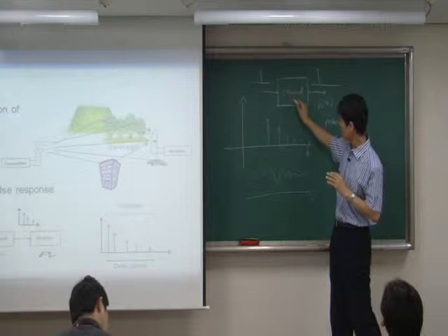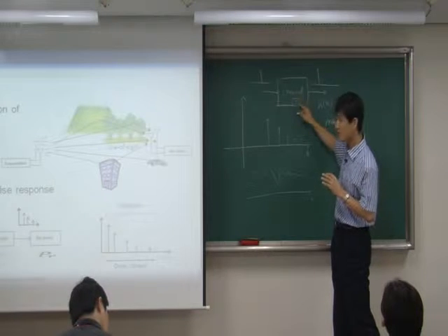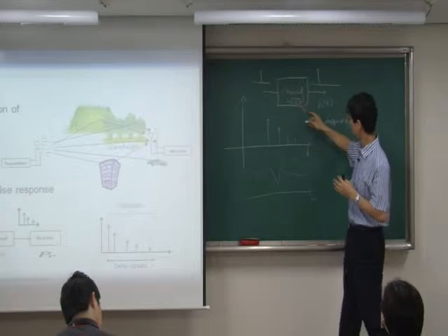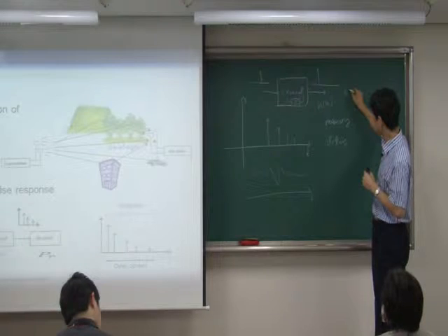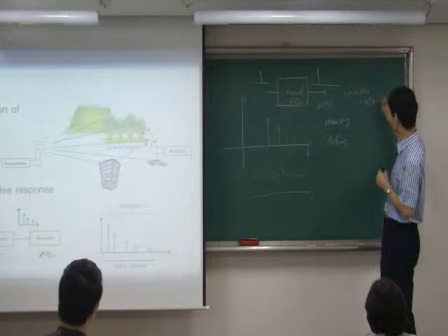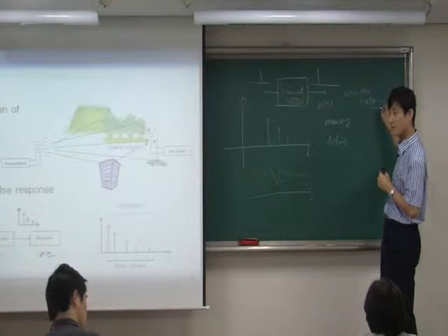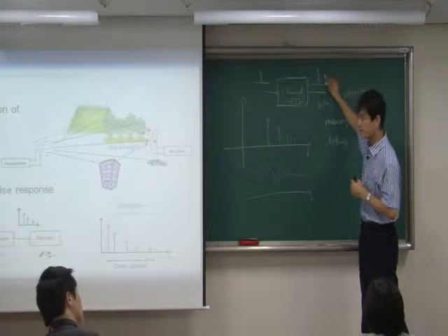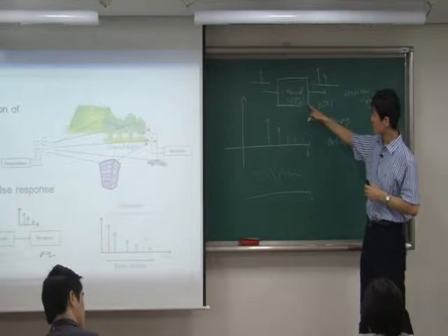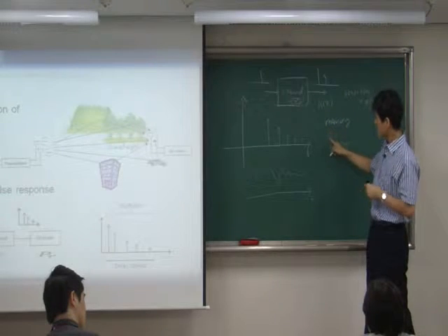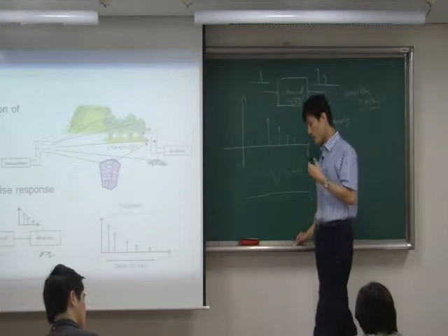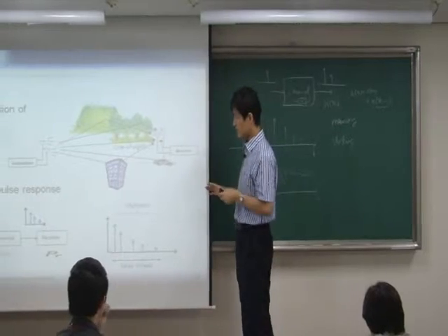Think about the channel in here, you have a delay component, like a z inverse, right? That's a delay component in a block diagram. If you have such a thing, now think about signals and systems, your output will have some input plus some other input with the delay component, right? You'll have some delayed component. This will create another impulse here, right? Because of this delay component. So when you have memory in a certain block, in this case especially, that's exactly the same as having a delay component. So sometimes you have a memory channel, delay channel, all these things are the same.